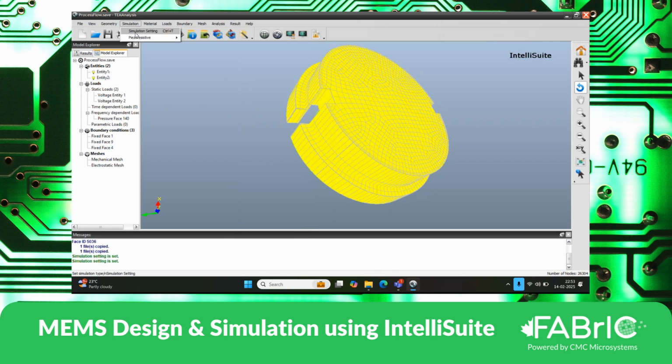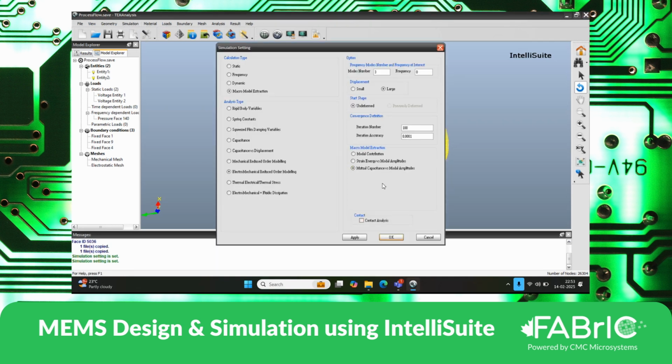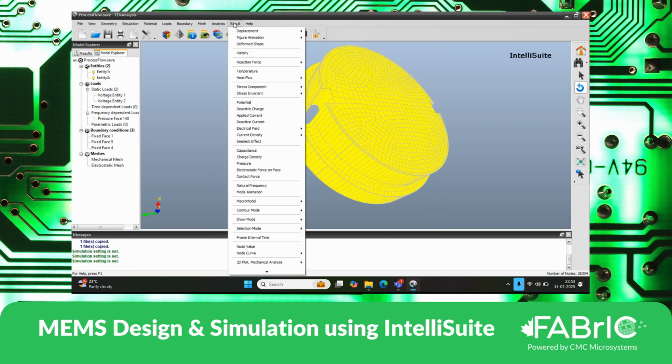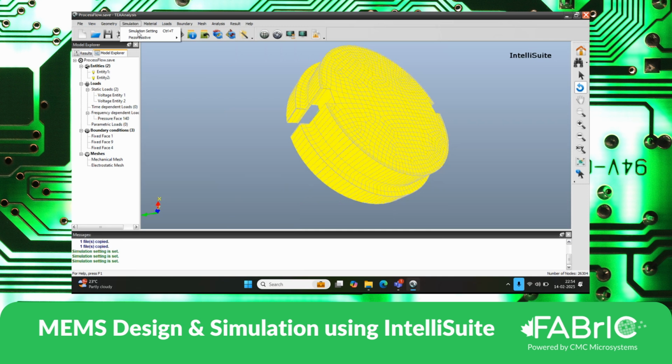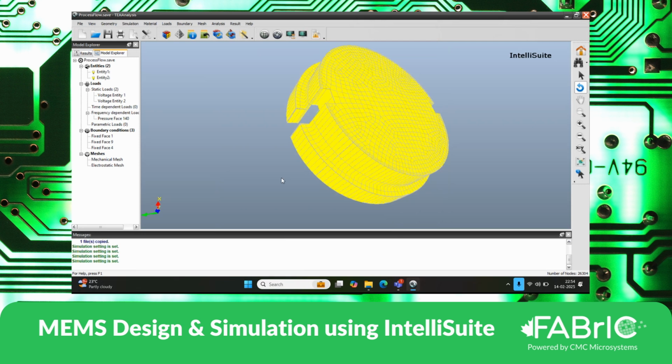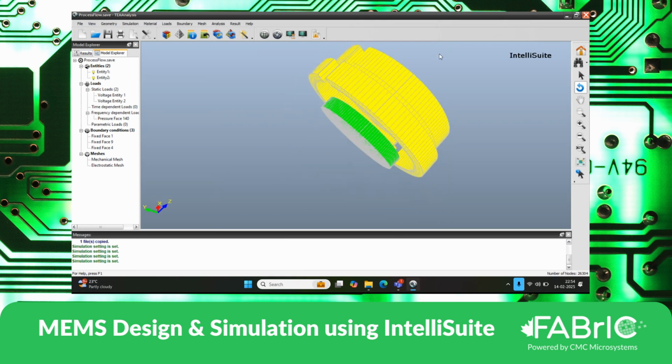Next comes the mutual capacitance versus modal amplitudes, because this is an electromechanical based simulation. Mutual capacitance is always a part of it. So we select that and then redo the simulation again. Once that is done, we go to macro model, then we check the mutual capacitance versus modal amplitudes. Once we complete all these 3 simulations, we are good to go ahead with system integration.